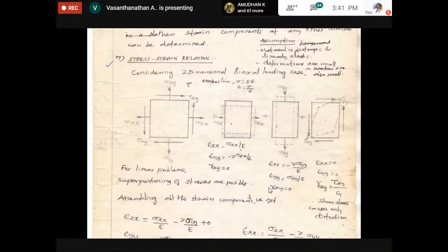Why do these deformations need to be small? You just think about that. In strength of materials, we have beam problems, simply supported beam or cantilever beam. And you are calculating using some analytical formula, y max equal to, theta max equal to. In all the answers you can see that it will be very, very small only. So y will be around 0.001 millimeter or meter, something like that. So your deflection should be very, very small, or else what will happen? The object will fail.